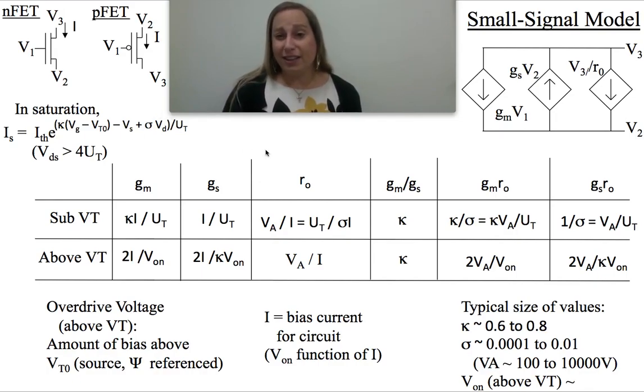Now, at first, you might think this is a lot of voltage-controlled current sources, and a lot of students actually get very nervous about, oh my gosh, that was the part of the circuits that was hard. I'm like, it's actually not that bad. It's actually in some ways easier because now it's dependent on a single voltage. And what you'll find is many times, for example, if I was doing a common source amplifier, this whole current source goes away and I just have these two to do my analysis.